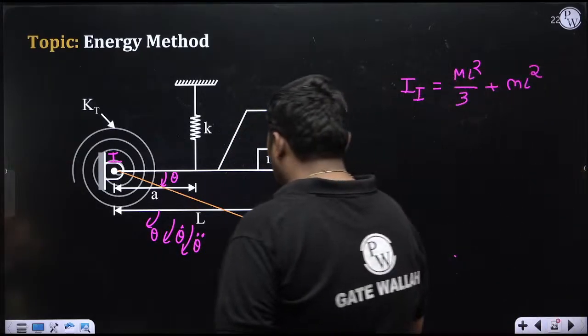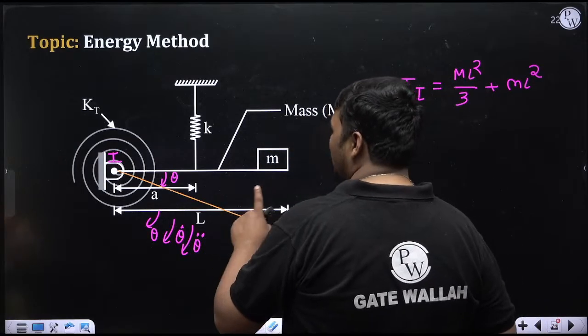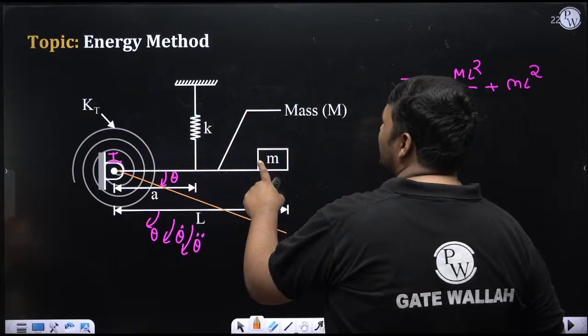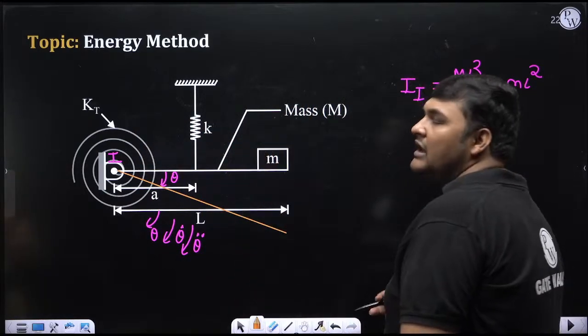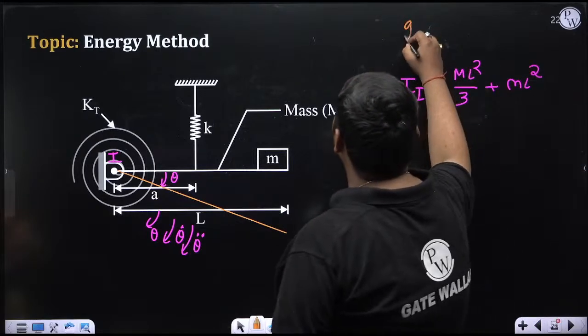Yes. Now what about gravity? Is there a role of gravity in restoration or not? No, because the weight of the system is supported by the spring, so in mean position due to weight there will be static deflection in the spring, and they will cancel each other's effect. So there is no role of gravity in restoration.